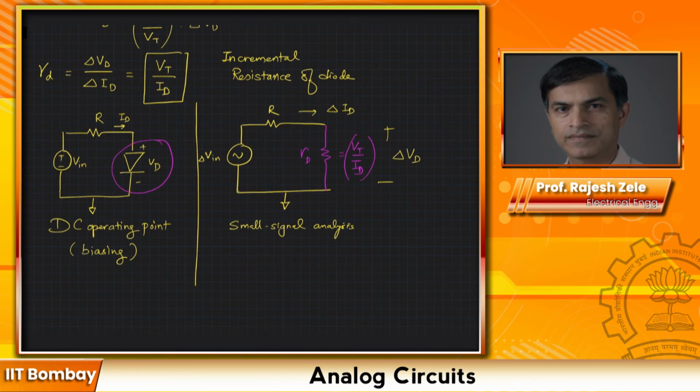Okay, so let's recap again. When you're given a circuit, any circuit, the first thing is you figure out just by looking at the circuit, is the diode going to turn on? You make an assumption and you say that, okay, the diode is turned on. In our case, it was very easy. Earlier case, it was 2.5 volts. So we would say that the diode should be on.